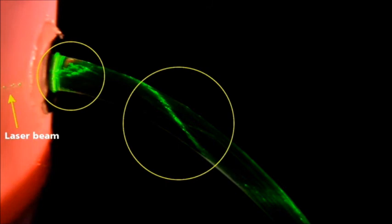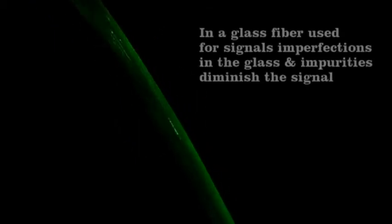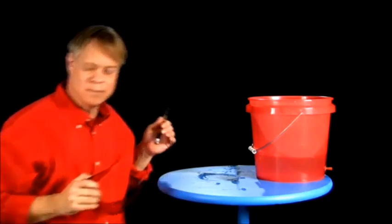That's because the interface with the air is uneven, and the rays that make up the beam strike at slightly different angles. When that beam makes its second reflection, those individual rays diverge even more, until by the time it reaches the third bounce, many of the rays are no longer at the critical angle and can exit from the sides of the stream. Here it happens in a few inches, but in a cable like TAT8, the signal travels a stunning 50 kilometers before it needs to be amplified. Absolutely amazing. I'm Bill Hammack, the Engineer Guy.